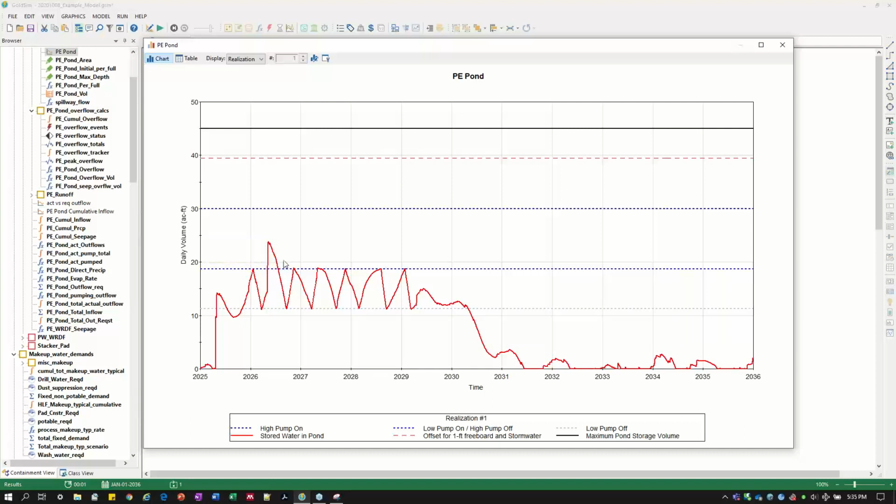So you can see that that pump is working and it's drawing water. I'm not showing that here, but the water level is being controlled, and there's still some water coming in to keep this rising, but this is actually pumping. And as we start to come down, we're still pumping until we hit this low level off switch. So it doesn't stop as soon as I hit this line, it stops when I hit this low level line.